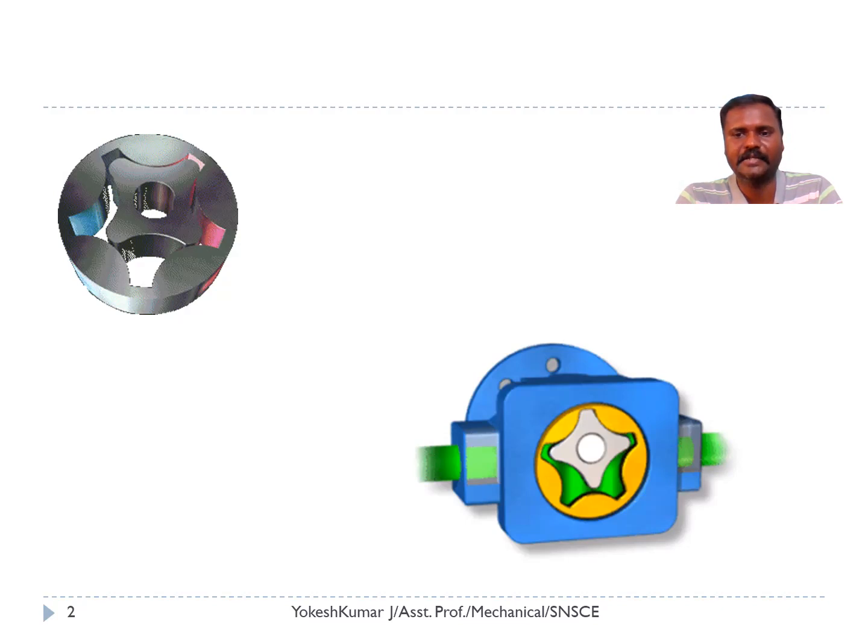The mechanical action of the pump draws the fluid from the reservoir, and due to the volume reduction, it pressurizes the fluid. The pressurized fluid is then sent to the direction control valve. The direction control valve directs the fluid to the appropriate location of the motor.